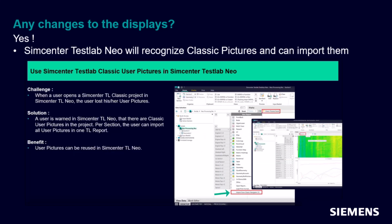Or if you use the pull down to create a new picture, at the very bottom of it there's the same option to import from Classic. We don't go the other way. The Neo pictures have a lot more functionality, such as queries and stuff like that, that Classic doesn't support. So we can't take the Neo pictures back to Classic, but we can take the Classic pictures to Neo. If you go back and forth between the two and create new pictures in Classic, you'll be able to come back to Neo and import those new pictures you created.